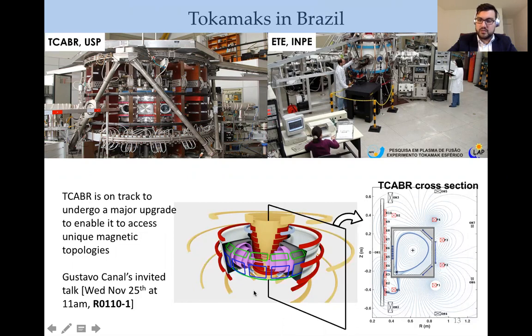So in addition to all the ordinary coils that surround every tokamak plasma, 2 sets of coils are being designed, the green one and the blue one here. Essentially those are called the correction field coils, and they will allow for unprecedented flexibility in the magnetic topology. A cross section is shown here in black, and the plasma goes around the vessel here.